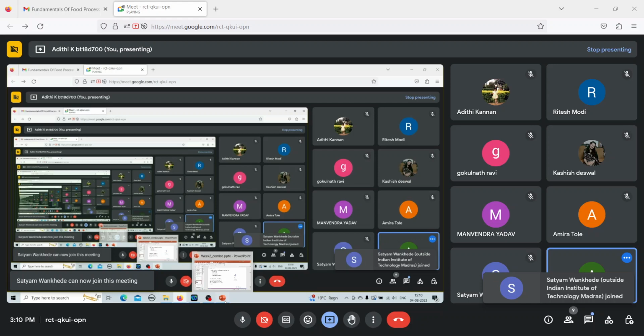This is because of the elastic nature of the material. And then after a while, you can see a gradual increase in the strain. This is because stress is directly proportional to the rate of strain in case of a viscous fluid. So the viscous fluid will start dominating, and you will see a slow increase in the shear rate till your stress is maintained. So this part is because of the viscous behavior of the fluid.